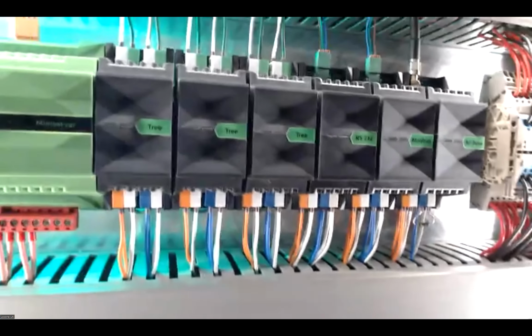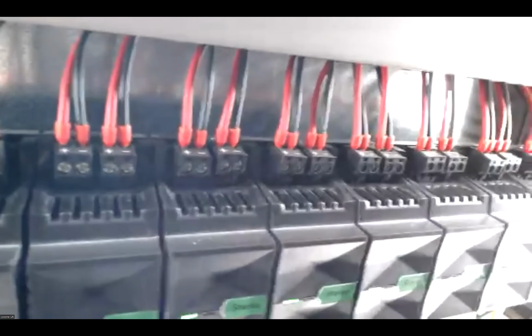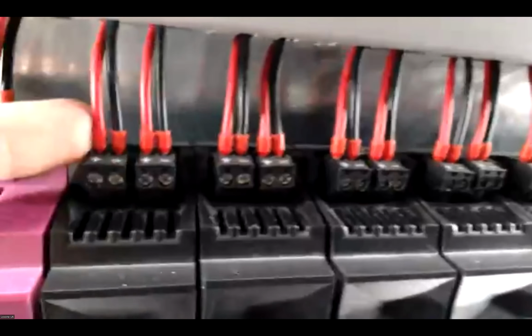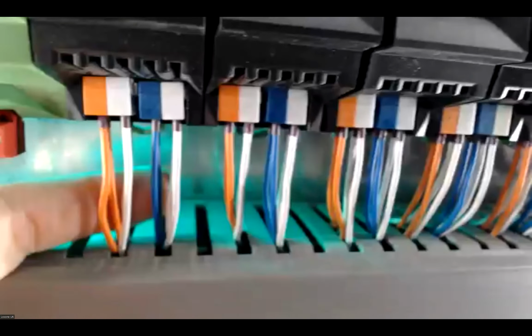For stranded cable, yes, absolutely. So something like the outputs on the audio server or stereo extensions, especially in the screw terminal, yes, ferrules are absolutely perfect. But for a solid core cable, maybe we just leave it as it is and we push it directly into the device.